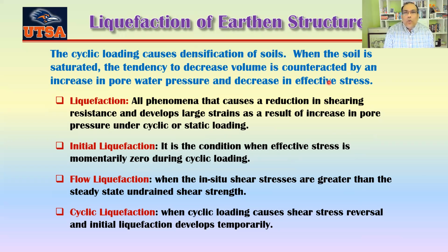So you are just trying to, let's say, shake something. This will try to densify. But if the soil is saturated, when this tries to densify, it creates pore water pressure. Now, if the pore water pressure at any point is equal to the total weight of the soil there, then your effective stress would be zero at that time.